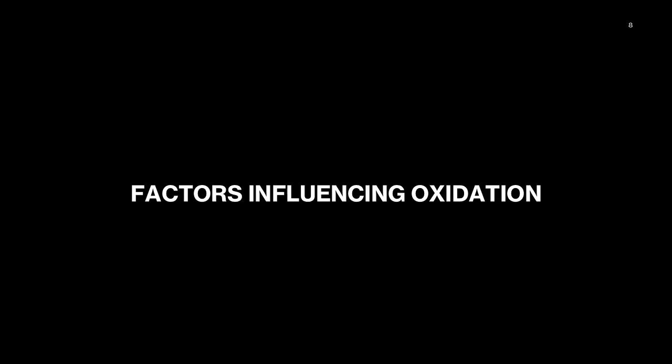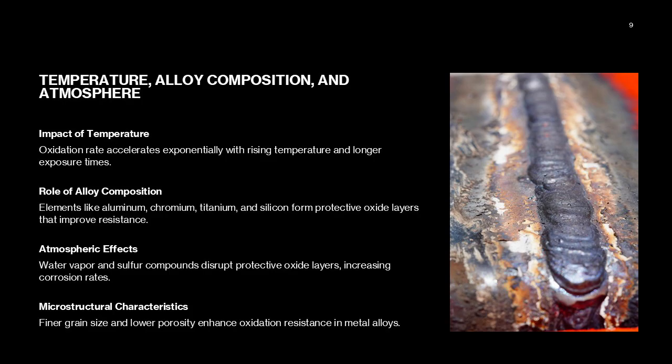Factors influencing oxidation: temperature, alloy composition, and atmosphere. Several factors govern the rate and severity of high-temperature oxidation. Temperature is the most critical variable. Oxidation accelerates exponentially with increasing temperature and prolonged exposure.